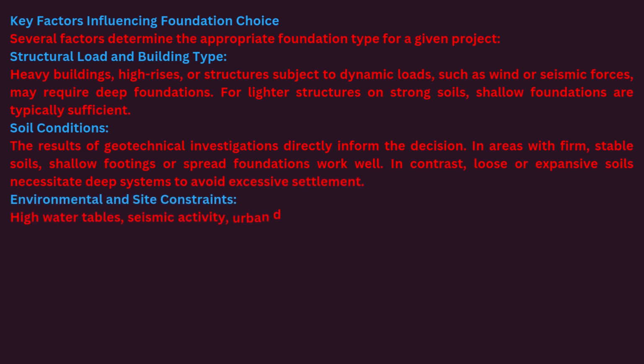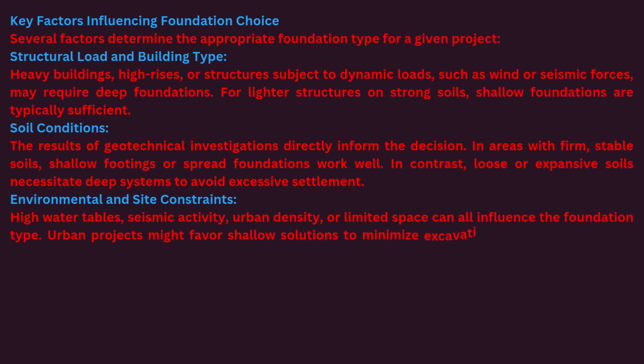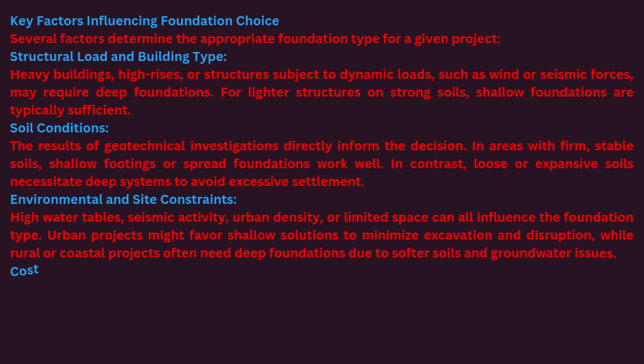Environmental and site constraints. High water tables, seismic activity, urban density, or limited space can all influence the foundation type. Urban projects might favor shallow solutions to minimize excavation and disruption, while rural or coastal projects often need deep foundations due to softer soils and groundwater issues.